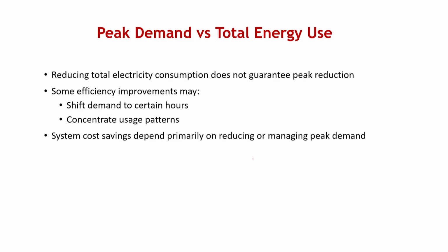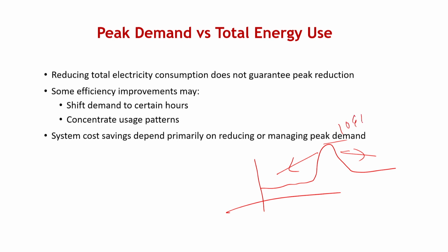So what we'll see in the next few slides is what specifically can be done around it. Suppose I have a system which is peaking at a certain hour. Can I distribute this peak in a certain way? As I said, about 10 gigawatt hour is my peak demand, and my overall average demand is 2 gigawatt hour. Can I reduce my peak by pushing some need to when my overall energy need is lower?